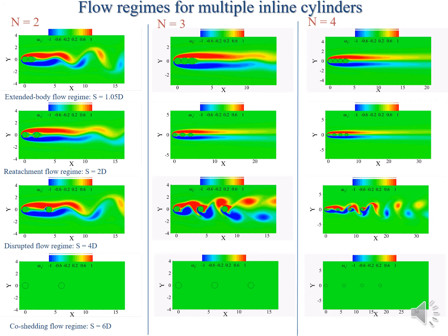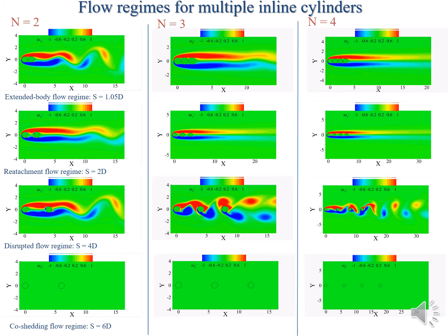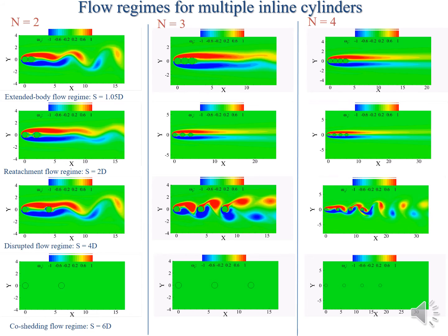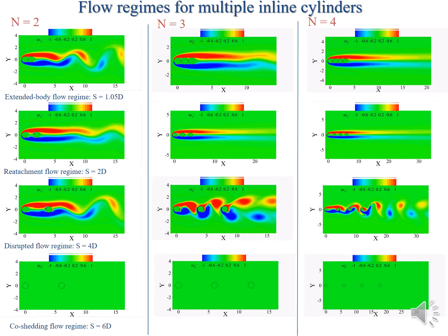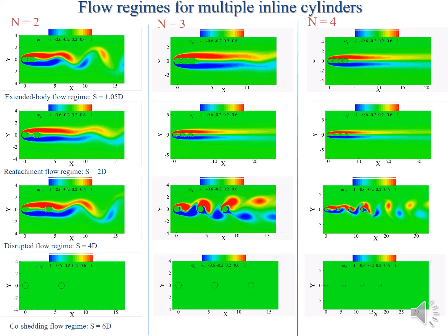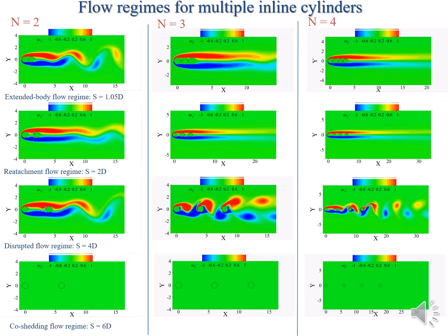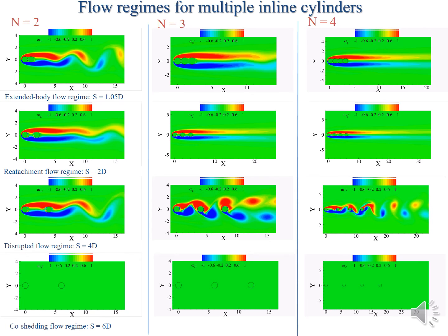we find that now we have a shear layer that is attaching momentarily onto the surface of the other cylinder. So we have a shear layer that goes and attaches to the other cylinder, but is momentarily disrupted because there is a noticeable development of vortices from the upstream cylinder. In most cases, we find that the vortices from the upstream cylinder develop, but they don't shed.